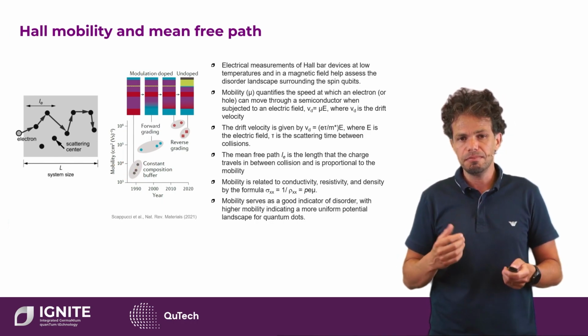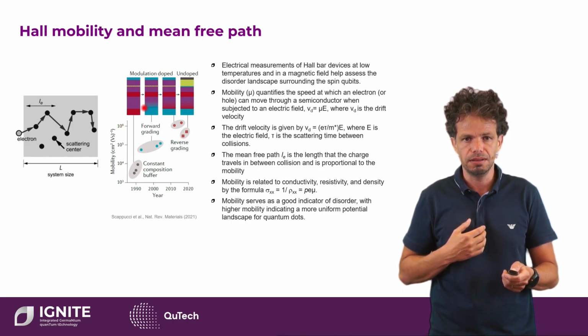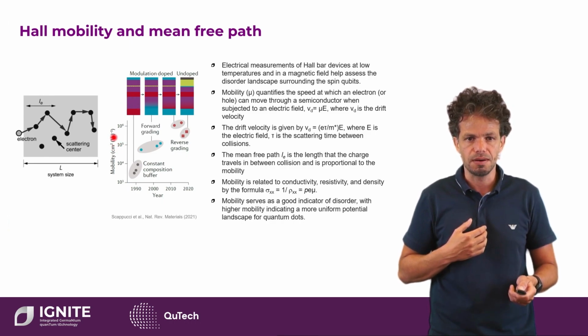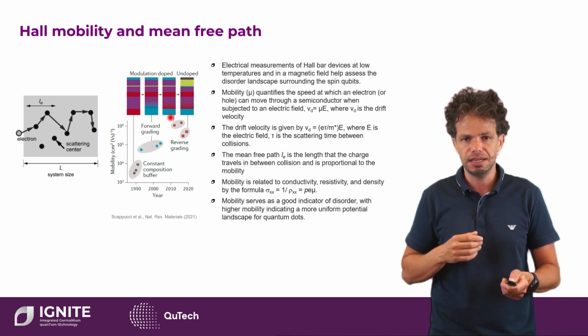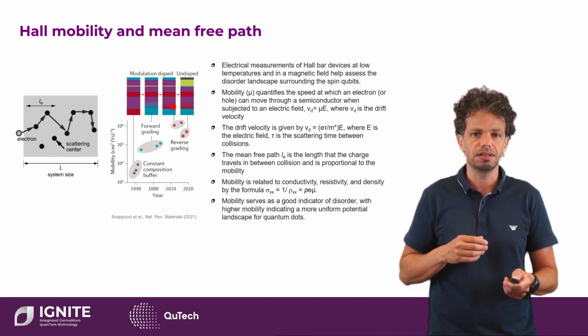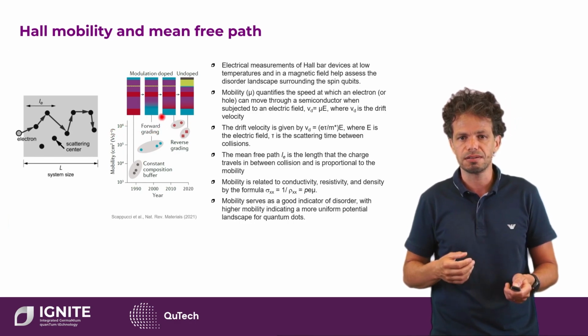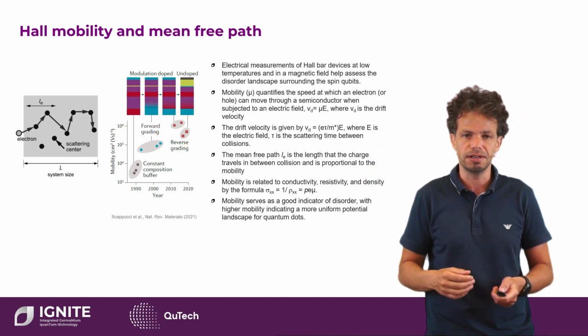Then a big improvement in the way we made the silicon germanium buffer layer underneath the quantum well brought us to mobilities around 100,000. And then around 2008, 2009 onwards, another improvement in the silicon germanium buffer layer underneath the quantum well took two-dimensional hole gases to reach mobilities of about 1 million or even larger nowadays.